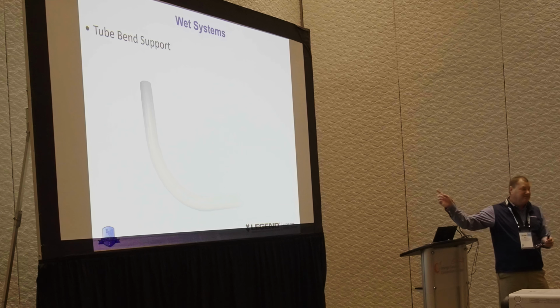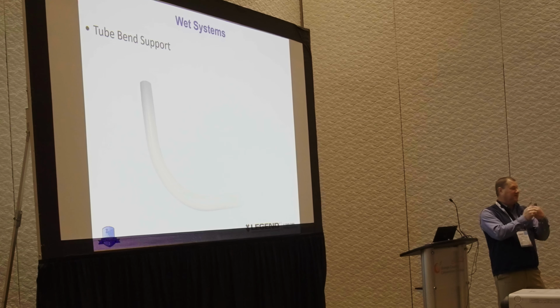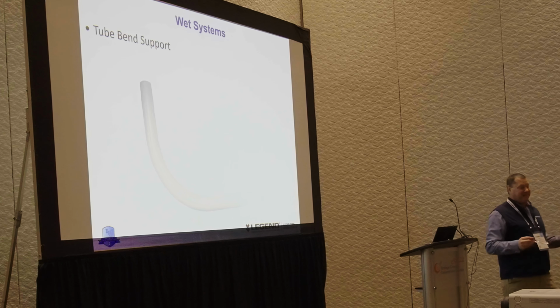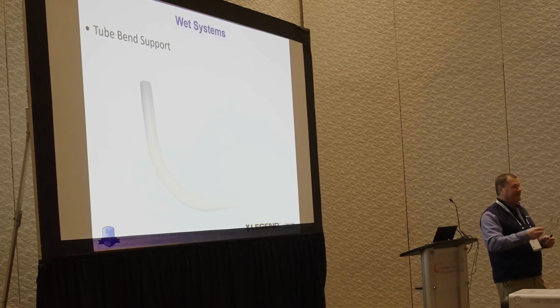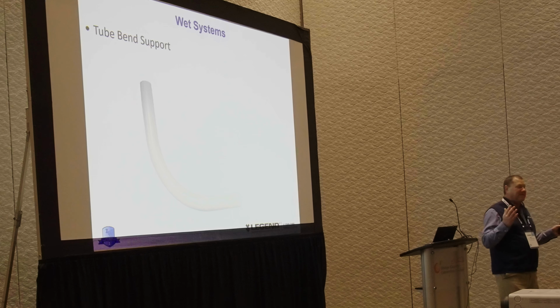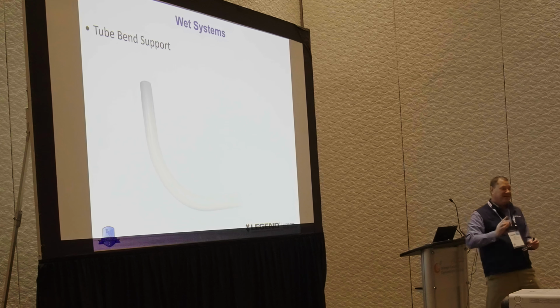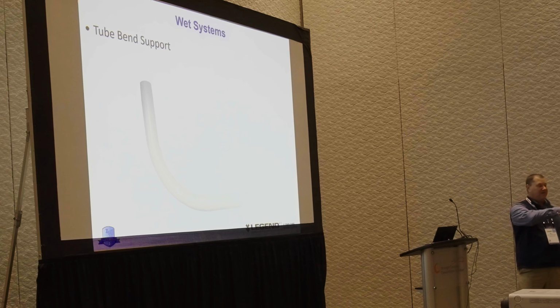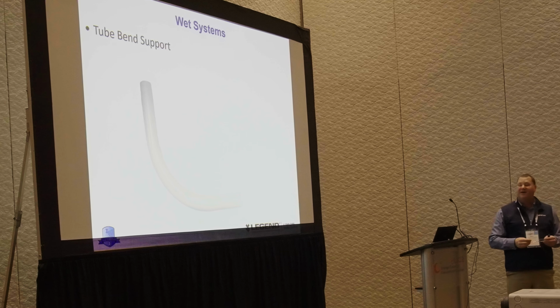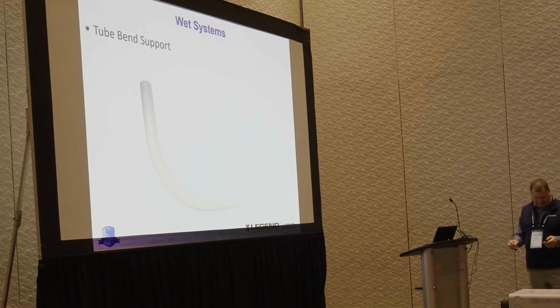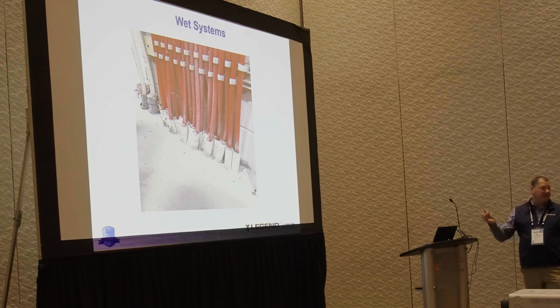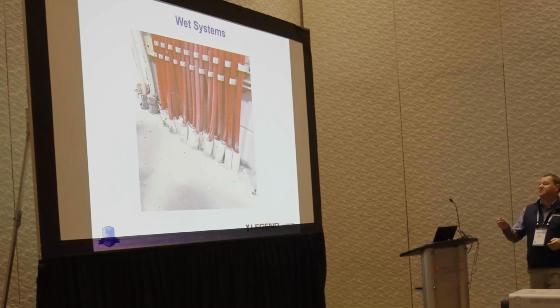And if I've got all of the tubing encapsulated in cement, because it can't expand and contract, where does all that expansion and contraction happen? It's going to stay in compression. Slab. Exactly. It's stuck in the slab. It's not going to go anywhere. But where that tubing is coming out of the slab, there's going to be some movement in that tubing. And if I don't have a tube protection sleeve protecting them from moving around, I could have some issues. It's required by the codes if you have a rating code, but it's just best practice.